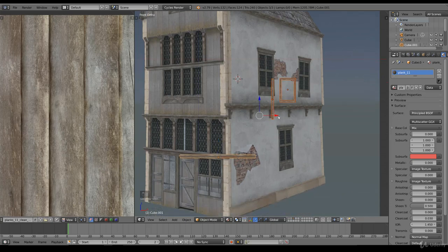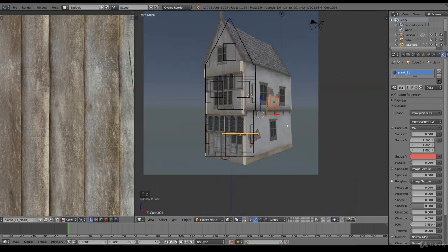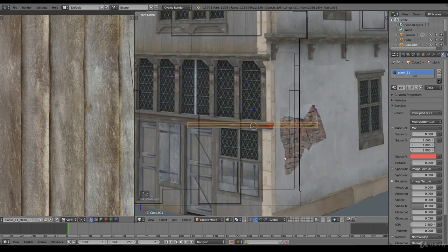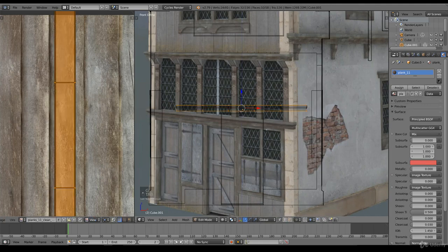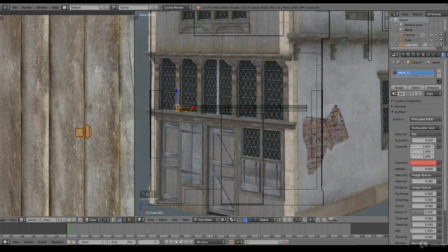So drag all of these to the first layer where we have the base of the building. All right, and we start with placing the wooden bar, or ceiling bar. In edit mode, grab the ends because it's not reaching these points. Press O, proportional editing. Make the circle a bit smaller so it won't touch these. So putting it right there, and these as well.